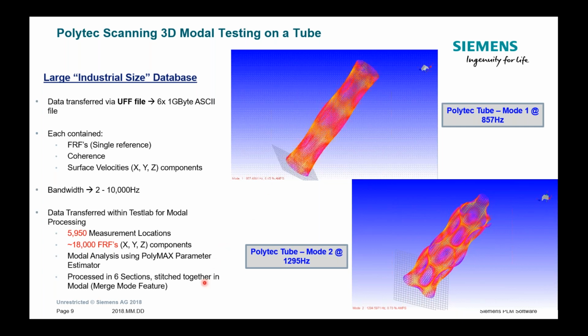Then in Testlab, what we could do was stitch all those data sets together, and in the end we come up with a complete tube, which we used for our analysis. That was in the bandwidth from 2 to 10 kilohertz. These were extremely large files, universal ASCII files, and there were 6 of these at 1 gigabyte apiece. So that's a lot of data to deal with, but it also shows that Polytec is used to those sizes of data sets, and that we could transfer that data through universal file and get it into Testlab.